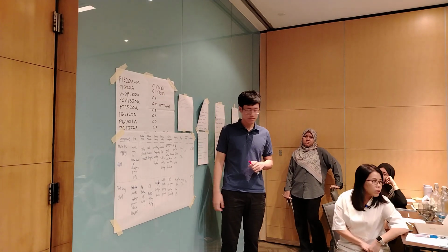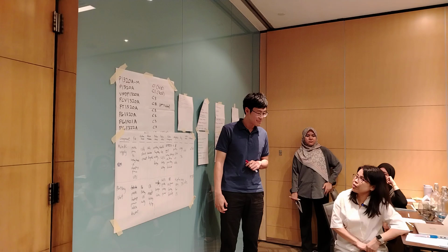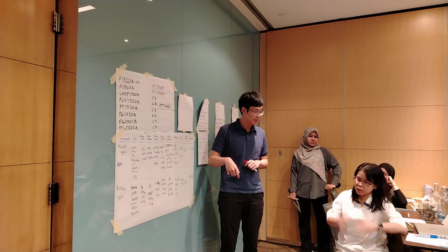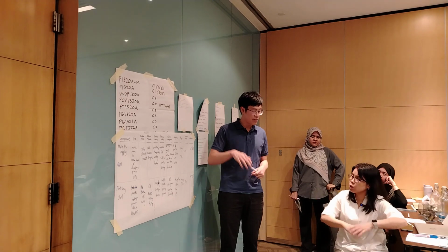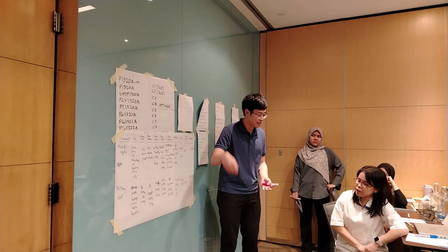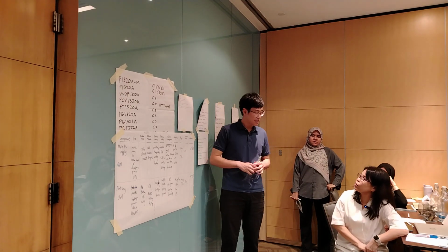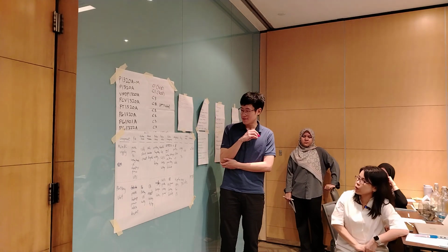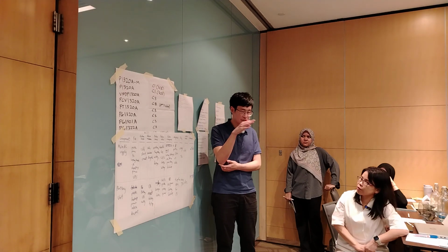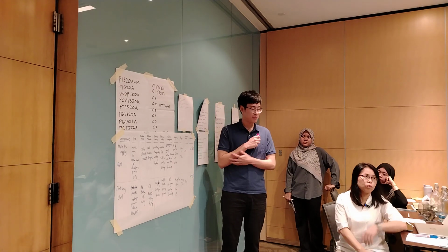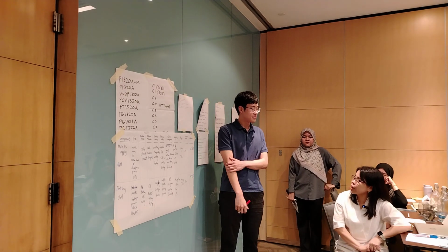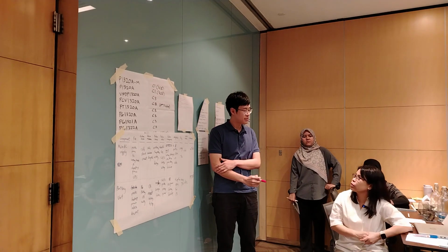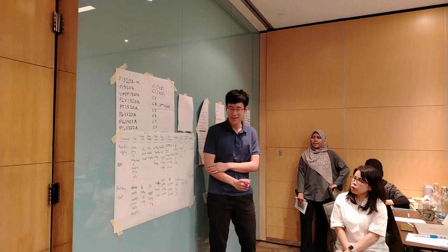But for us, we can see the cables. The cabling at the UPS itself is short, but the actual cable, we can see outside. The connectivity we can see. In that case, we can do the inspection. The visual inspection could be the task. You do the visual inspection: is there any dirt, loose connections, or vibration around the area? Yes, sure, that one can be done.